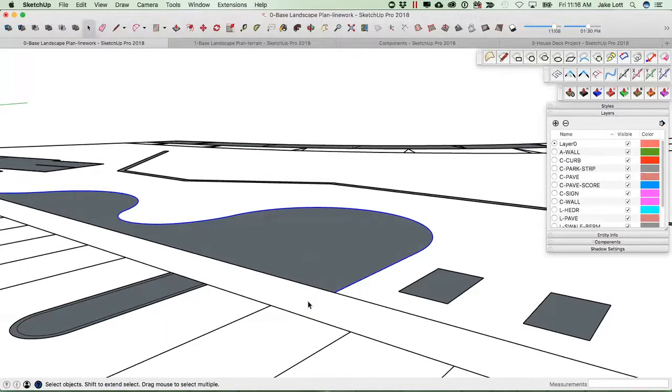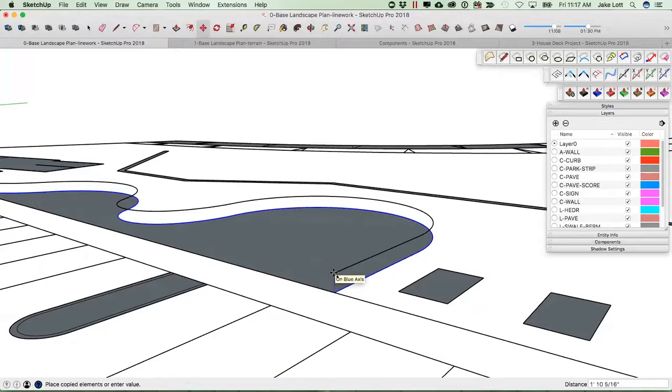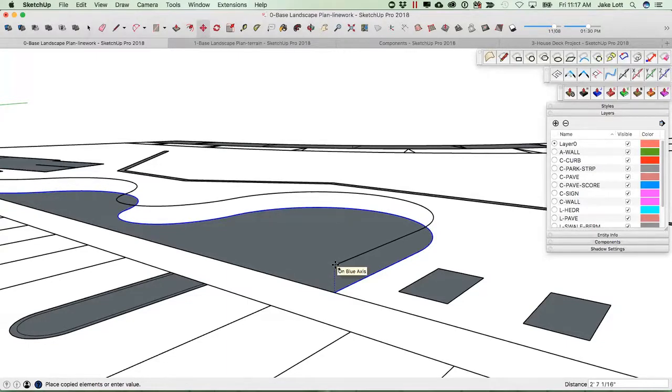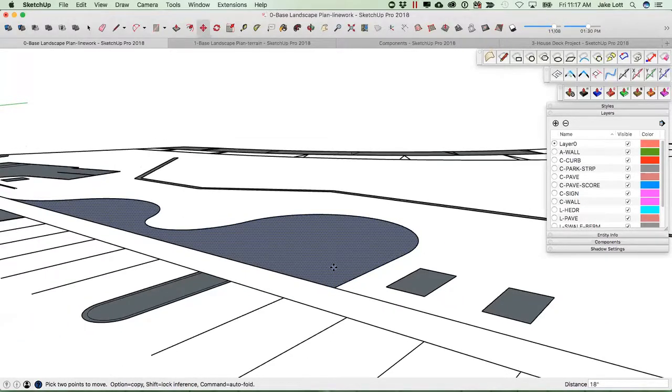So now, if we wanted to extrude this up, this might be something that you've done or wanted to do, is we can't push pull up just a single line surface, but we could make a copy, by holding the control key and bringing up a copy of that line however high we want. I don't think it worked.